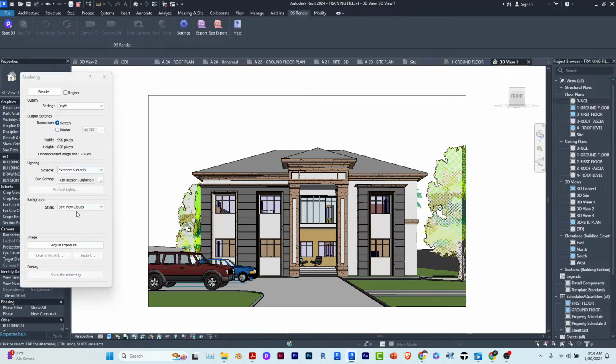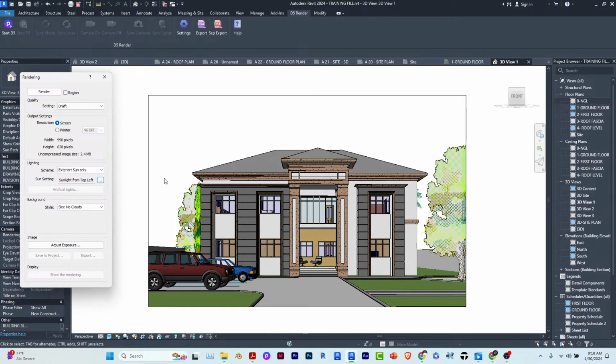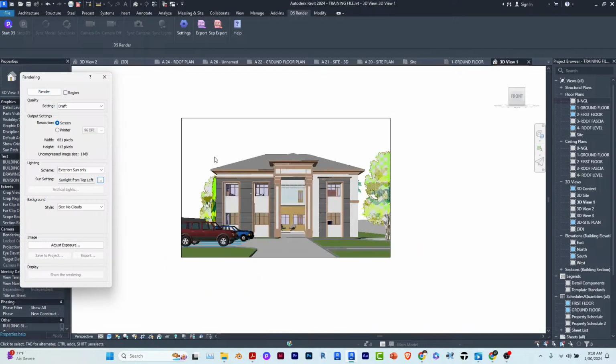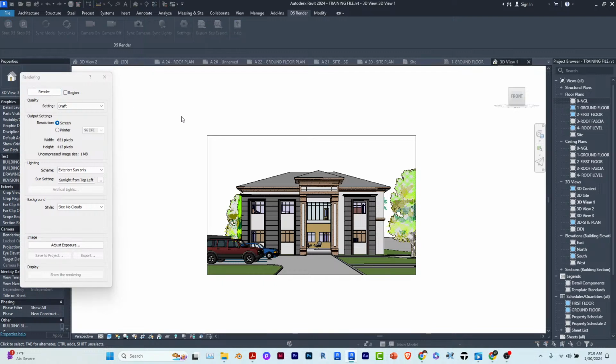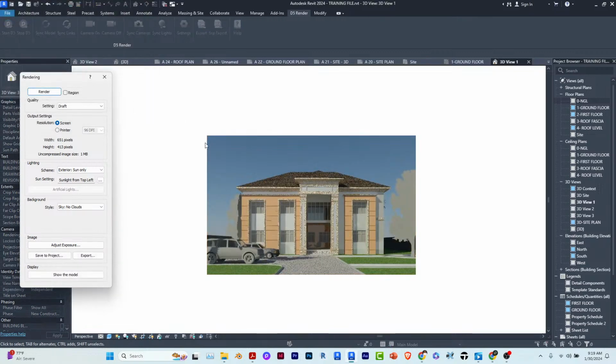And once you've done the rendering, you can decide, okay, I don't want any clouds. You can turn on sun only. You might do some settings here for the clouds. Maybe top left, top right. You might change one or two things here. And then you might also just zoom in a little bit to reduce the size of the draft I want to create and go ahead to run a test render. So I'm just showing this basically to tell you Revit can render, but I would advise if you want to render to try other dedicated rendering softwares instead of Revit.